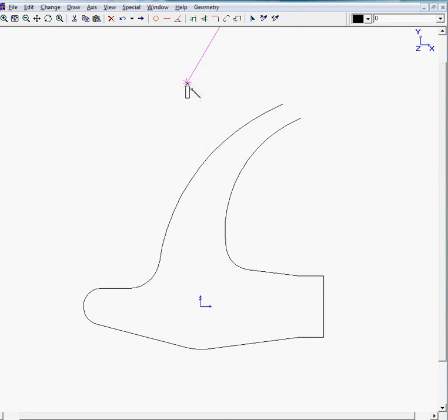We click on OK, and you see that a line is being attached to your mouse cursor, and you can now place your line on a snap point. In this case our reference point is a snap point. We click on the reference point and there's a line. If this would be necessary, we can define even more lines. In this case this would not be necessary, so we click on our right mouse button and it's being deselected.